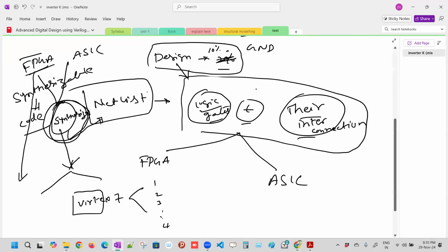Among these, let's say you are taking the Virtex second family, then that is the setup you do before synthesizing. You set the family and which device you are choosing, everything, for the synthesis. Then you perform the synthesis. Then only the netlist is generated.